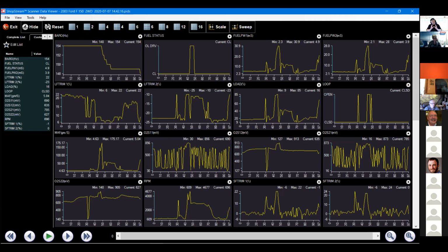So here's what we start to think, or at least I start to think. I look at it and say, why on a mass airflow controlled vehicle, how could I have a supremely positive on one bank, negative on the other? How could my fuel trims be opposite? Well, there are some basic things that come to mind, guys.